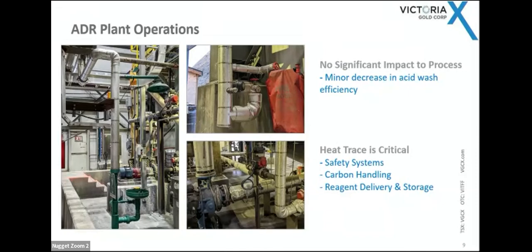So right here, if you notice, there's an open door, and this is a firewater. This heat trace didn't used to be there. You can probably figure out why it needs to be there, right? This is a safety shower. You don't often see heat trace on a safety shower, okay?